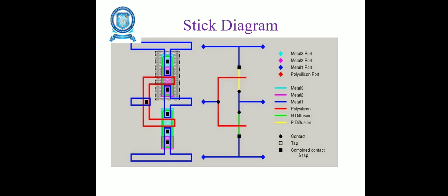These design rules serve as the communication between the designer with specific needs and the fabricator who materializes all those. The goal is to convert circuit principles to silicon, and stick diagrams may be used to represent the layer information using color coding.